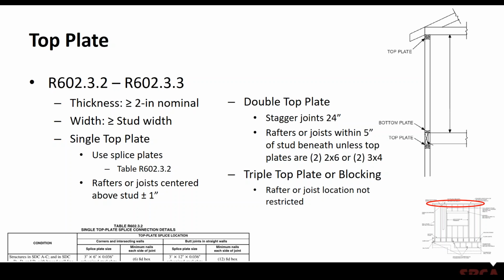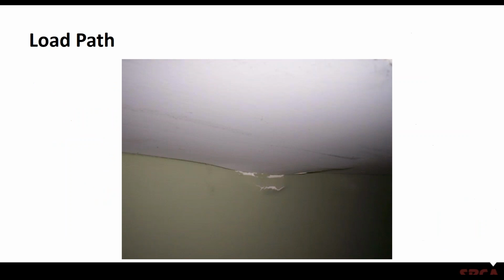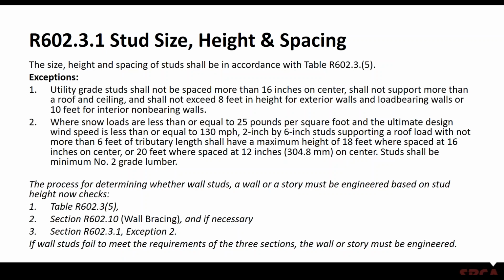But now we're talking about rafters or joists or trusses, not girder trusses, not girders, not beams. Those you're required to get some type of a column in that wall. And if you don't do that, you can certainly end up with something like this, where you get some severe crushing that takes place that ends up showing up through the gypsum.